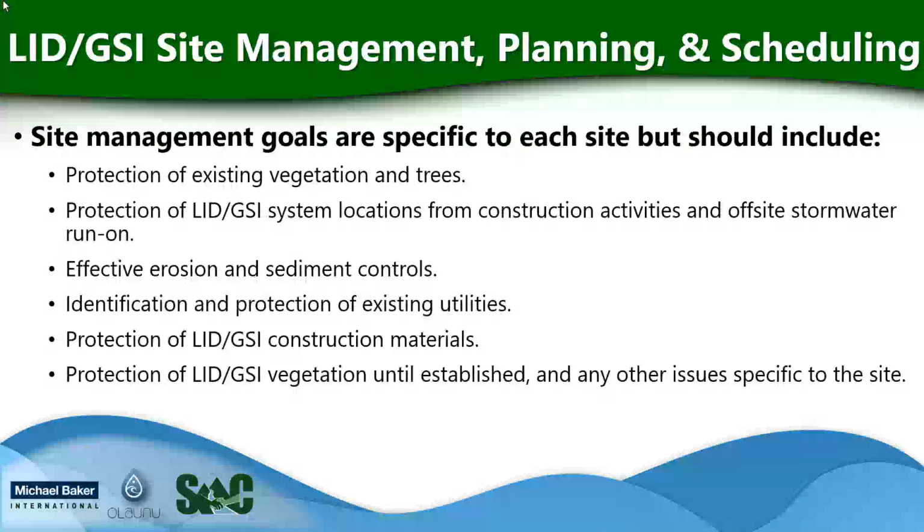Critical to integrating into sites is an effective combination of erosion and sediment controls. Also, identification and protection of existing utilities, and protection of LID and GSI construction materials to make sure that they are not contaminated or out in exposure for long periods of time. And finally, protection of LID and GSI vegetation until it is established, and any other specific issues to the site.